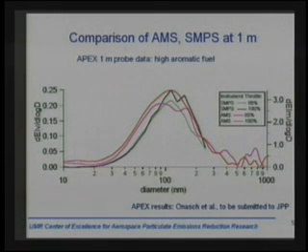As Phil pointed out, if the probe is operating right at 1 meter, the way we set it up with dilution, we should only be measuring the carbonaceous particles, and actually shouldn't be seeing anything with the AMS. And the AMS is a good indicator of whether we're making that measurement properly or not. But typically, we always see some small level of condensation on the soot particles. It doesn't affect their size or mass significantly, and we can measure that to see if it is affecting it.